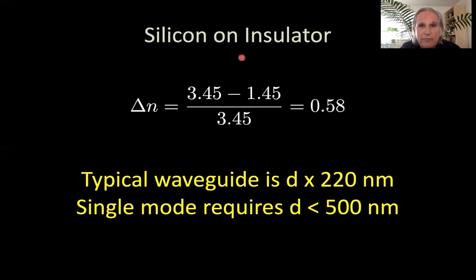However, silicon is a rather odd material in that it has what's called a native oxide. That native oxide is silicon dioxide, what we make glass out of. So if you have a piece of silicon, which has quite a high index, 3.45, and you put it in a wet oxygenated atmosphere, you get an insulator, glass, which is also sand. Glass is actually sand that you heat up really, really high. You get this thing that has an index of 1.45, like glass.